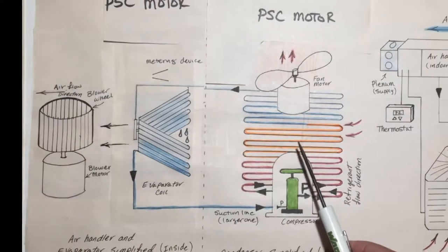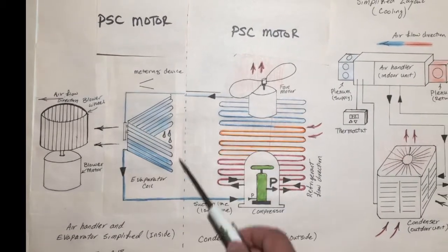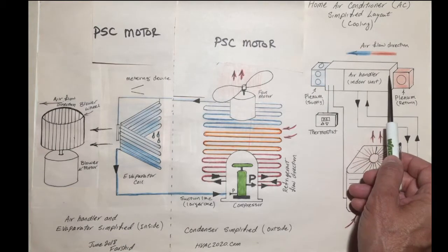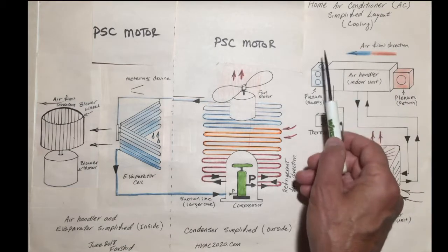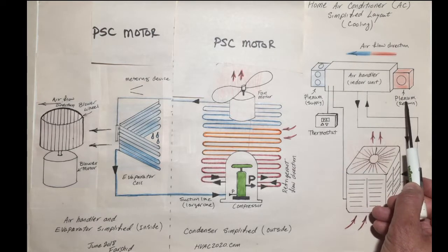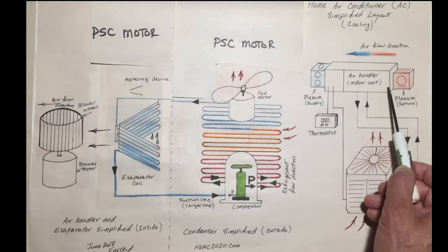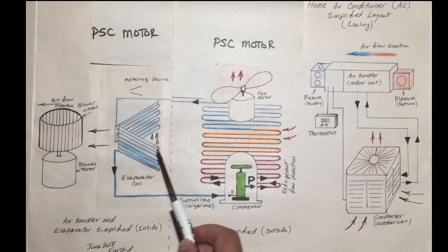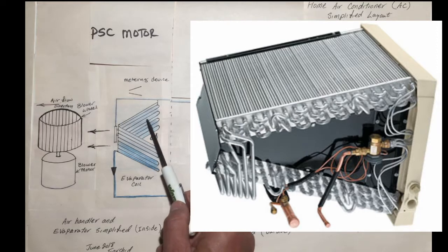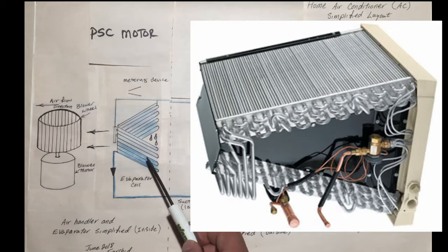So inside of our conditioned space, we have these components. Again, this is simplified, and what we have is air flowing from right to left, the warm air that we're pulling in through our plenum, through our return duct, passing through our filter, and it hits another coil. This one is laid out, it's referred to as an A-frame because it looks like an A laying on its side.